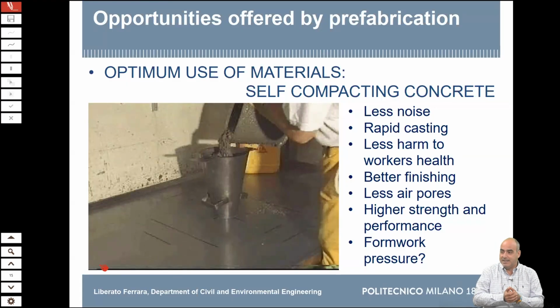So one of the SDGs that we were discussing before was also health and well-being of workers, who are not exposed to noise. When you vibrate with the poker vibrator and so on, one of the pathologies that construction workers suffer is dead fingers, because this alters your circulation. So if you reduce the vibration, that turns into better health for the workers. But also self-compacting concrete, which deaerates and consolidates, gives you a better finishing. Self-compacting concrete contains more fines, so you can produce more reliably a better strength concrete, and you can also have a less dispersed